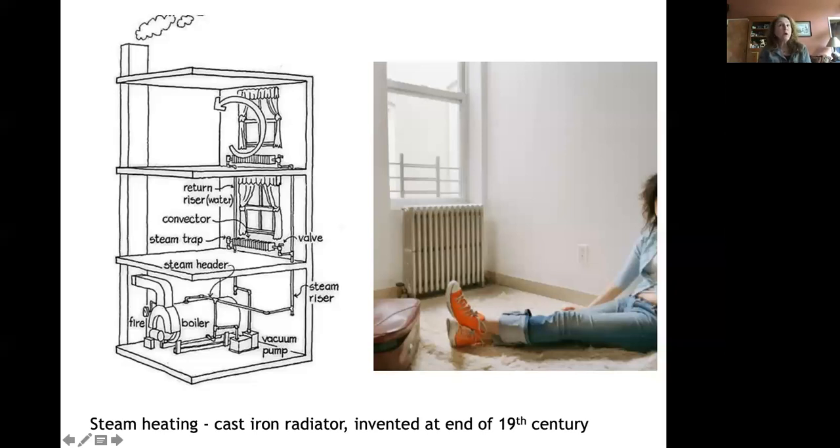You could do it with water. So we have a lot of water perimeter radiators, and those require bigger pipes though, so that's one of the disadvantages. One of the advantages is that you can actually have more control though. You're utilizing sensible rather than latent heat. So it's not just on and off like the steam, you can also have volume control. And this system is in Worcester.